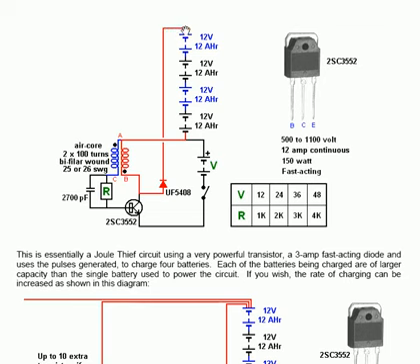The voltage on the battery driving the circuit is marked at V. If V is 12 volts, then the resistor R will be a 1K resistor. If V is 24 volts, then R will be a 2K resistor. With 36 volts, it's a 3K resistor, and so on. So there's a 1K for every 12 volts in the drive battery. The drive battery can be as big as your transistor will manage.